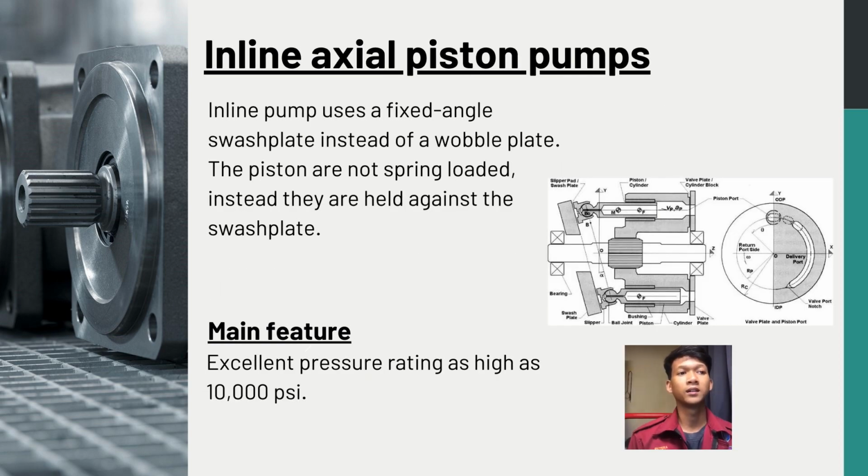Now let's look at the inline axial piston pumps. Inline pumps use fixed angle swash plates instead of a wobble plate. The pistons are not spring loaded and instead they are actually held against the swash plates.